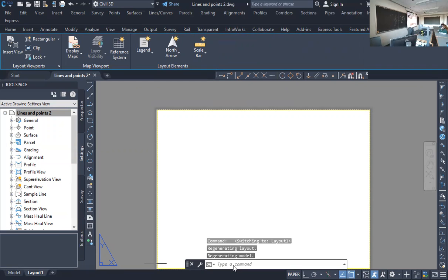Has anybody heard of external references, XREFs? External references are just kind of Lego pieces that you're going to put together to make something else. So your title block is a drawing you've made somewhere, hopefully you have it. More on that in a minute. That you're going to bring into you. It's just another Lego or another puzzle piece that I'm going to put in.